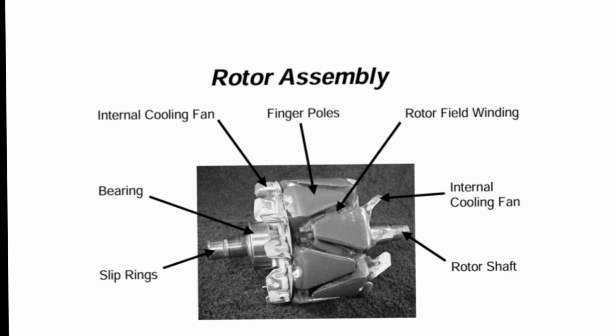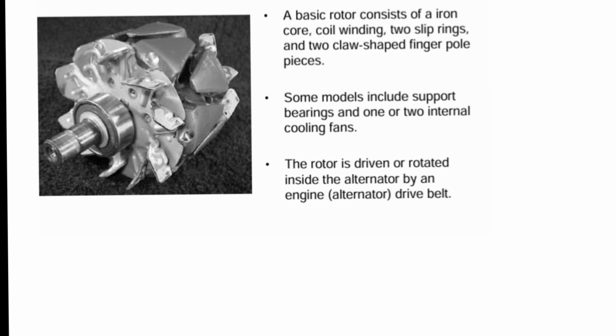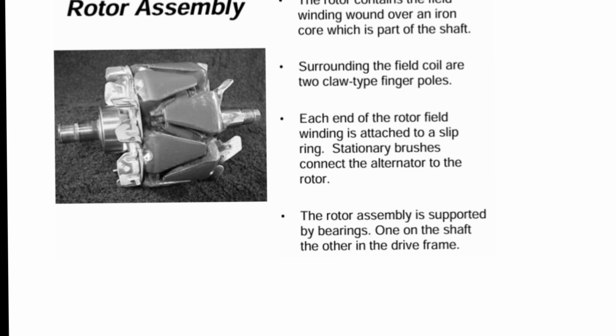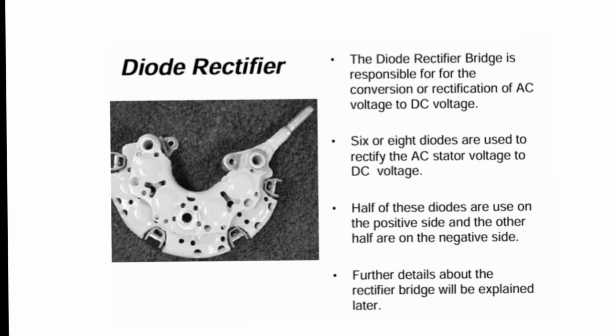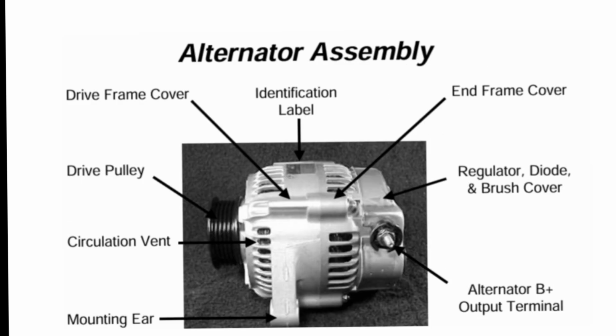Now let us discuss common failures. Battery not charging. Possible causes: broken belt, faulty rectifier, damaged regulator, open winding, low voltage output, loose belt, weak rotor field, carbon brush wear, overcharging, defective regulator, noise from alternator, bearing damage. Battery warning lamp on. Charging circuit failure. Burning smell. Short circuit inside winding.